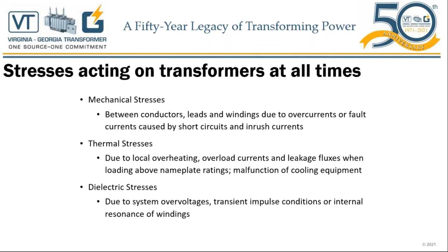Mechanical stresses are due to all these electrical fields and electrical forces that we discussed. And these mechanical stresses are between the conductors, leads, and windings, due to the overcurrents or fault currents caused by short circuits or inrush currents.